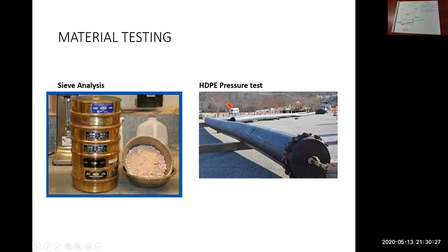So this other end of the pipe is where the water is pumped into the pipe. So possibly with a fire hose. So a 50 millimeter diameter hose is attached on the far end here. So it's blowing water into this pipe. You crack this valve open to let the air out. Some water will leak out as well, but the purpose is to fill this completely with water and then pressurize it to see if there's any leaks.